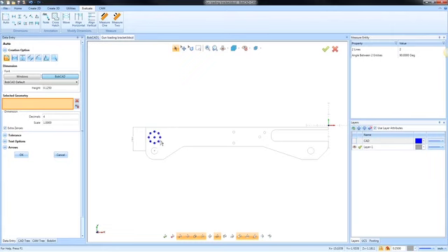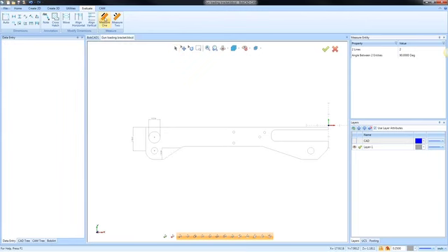So I could come in here and start measuring our hole locations, or I could figure out some angles or whatever it is to figure out what's going on here. But in this example, we have measure 1, measure 2 off of single entities or multiple entities, and then the other one is auto in order to start dimensioning or pulling dimensions off the part.